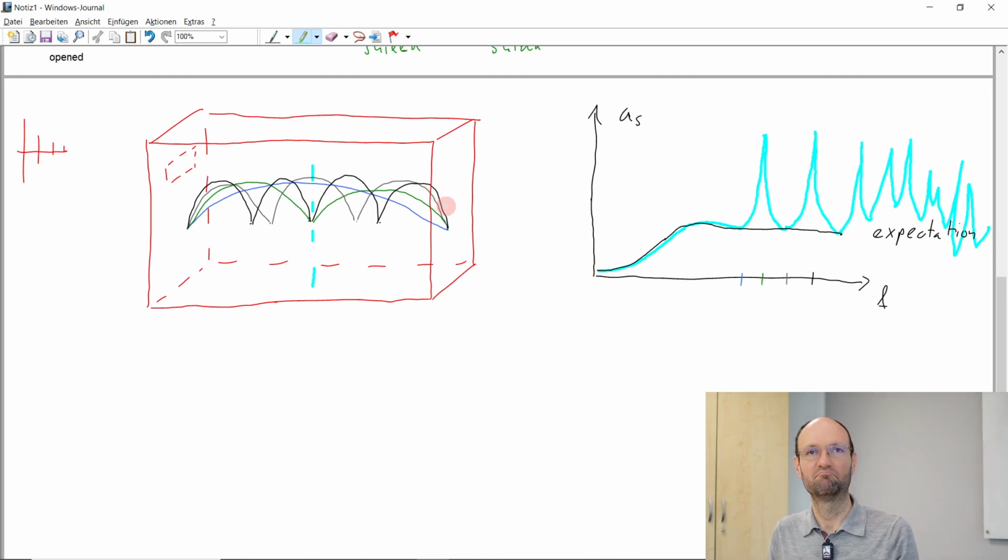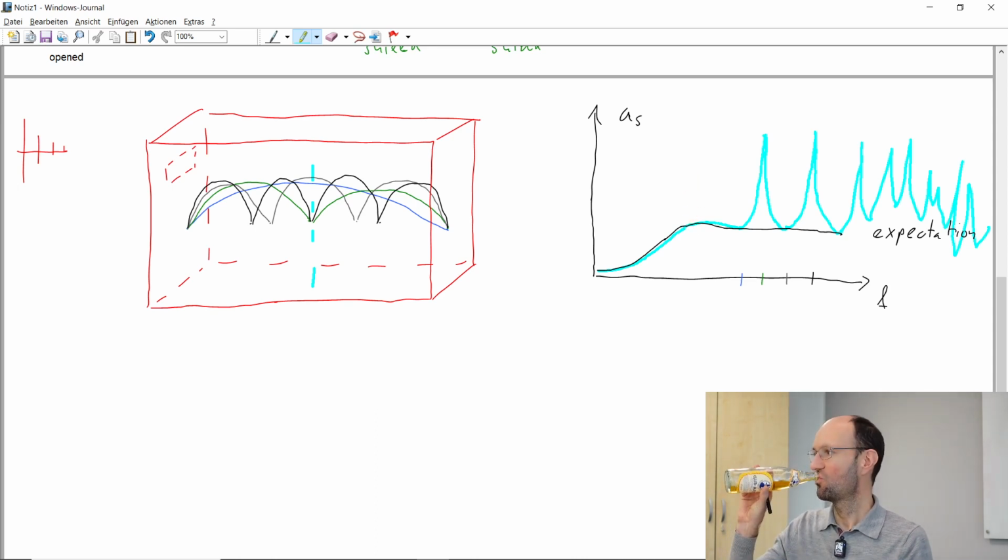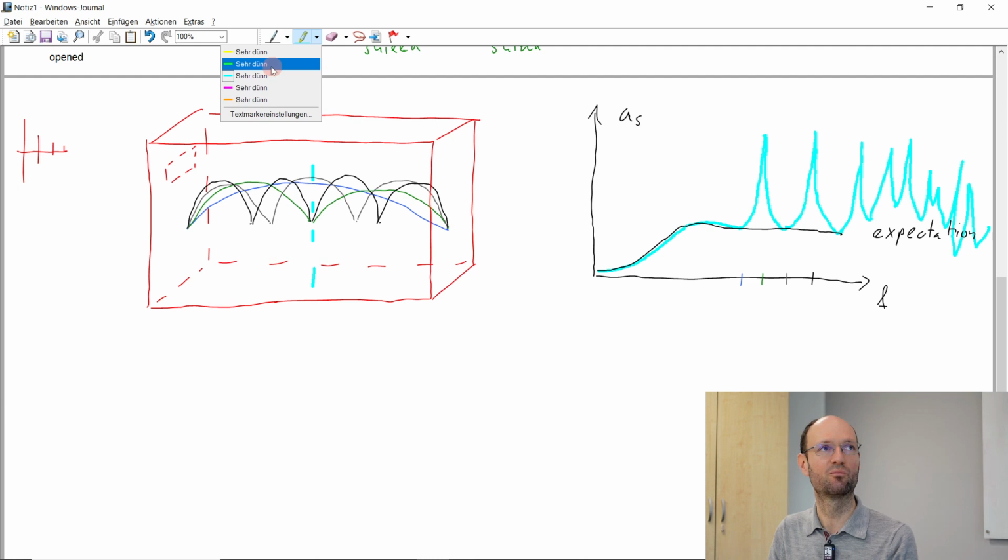And so what's the bad effect? It's not precise anymore. We get some measured shielding attenuation that is not our real shielding attenuation, that shows artifacts of the measurement position. So now we could change the antenna and maybe shift the antenna to this position here, for example.